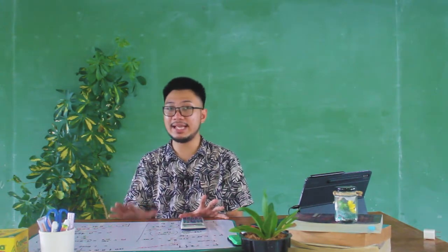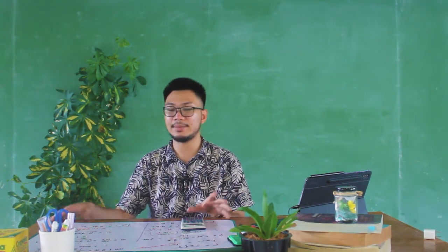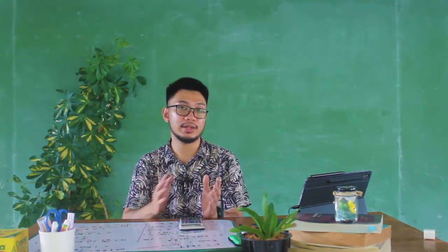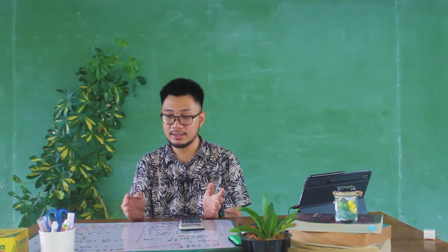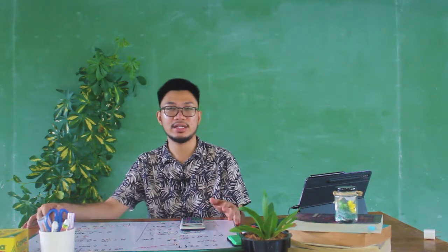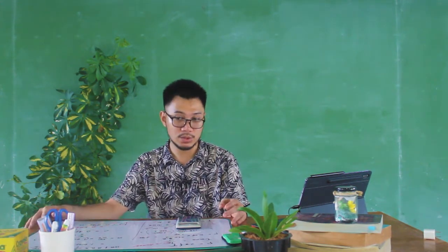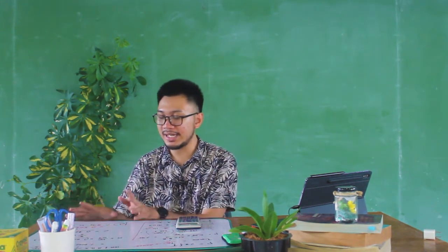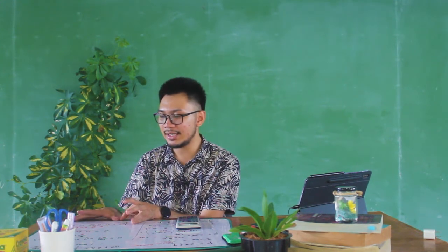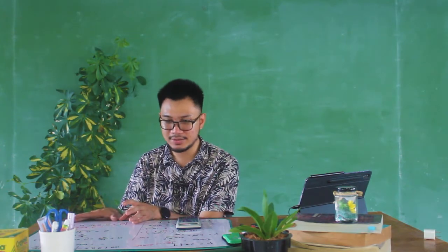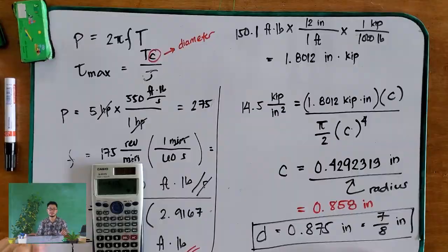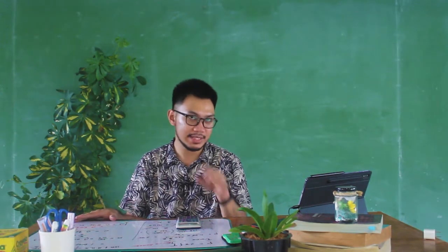So this one applies to all kinds of problems. It just repeats. Once you already know how to play with the torque, with the power, and with the frequency, then you can just go through all of those problems that you have in the reference that we use. So understood? That is how important it is. Then you will be able to design these shafts given the power, the frequency, and the torque, and the maximum shear stress or the allowable shear stress.